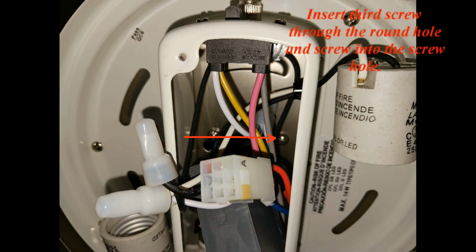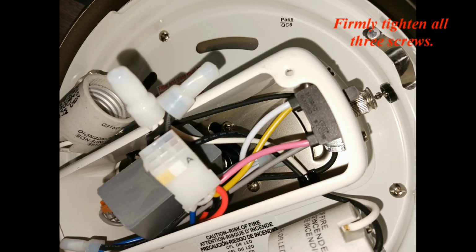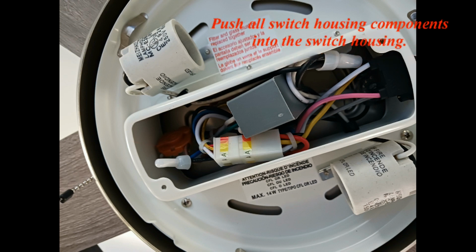Insert third screw through the round hole and screw into the screw hole. Firmly tighten all 3 screws. Line up the color marking on the connectors and connect fan housing connector with light kit connector. Push all switch housing components into the switch housing.